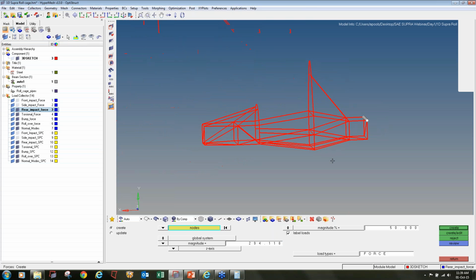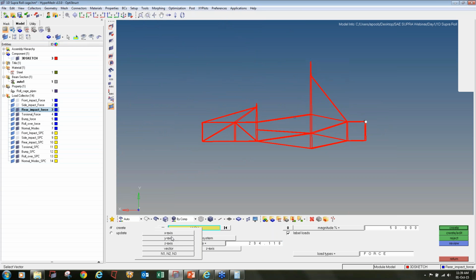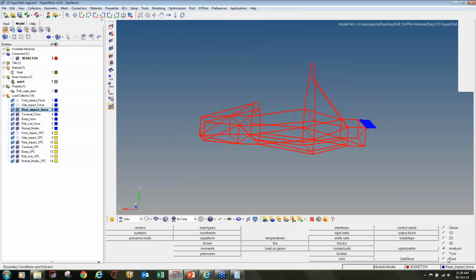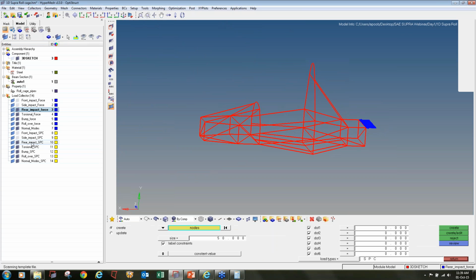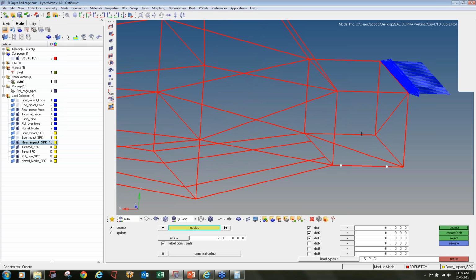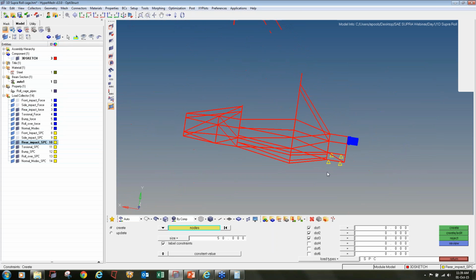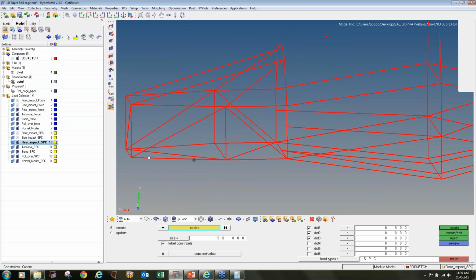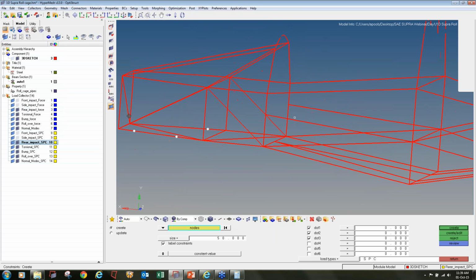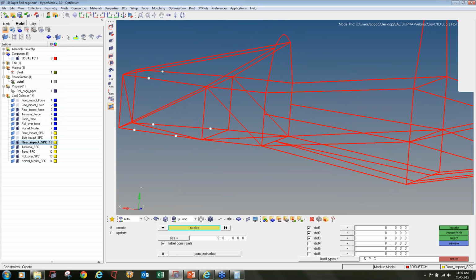Now the direction you can see here is x-axis positive. So I will say create and apply the constraint. So I will make rear as the current, turn off this and apply a constraint here on the suspension mounting points and front suspension mounting points, to all the 6 degrees of freedom, create.